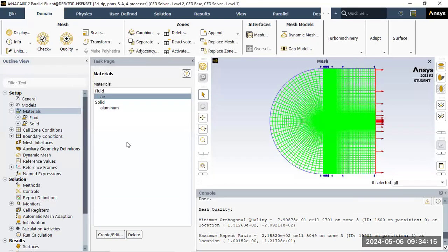Again, depending on your Mach number and Reynolds number, you have to figure out what your inlet velocity, viscosity, and density are, and then enter those values. Don't just copy-paste the numbers which I'm showing in this tutorial.